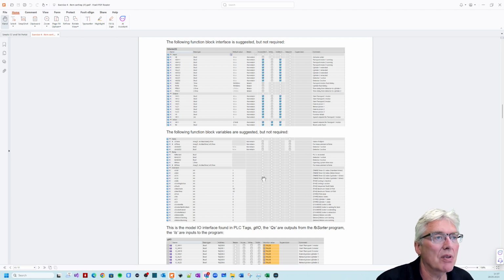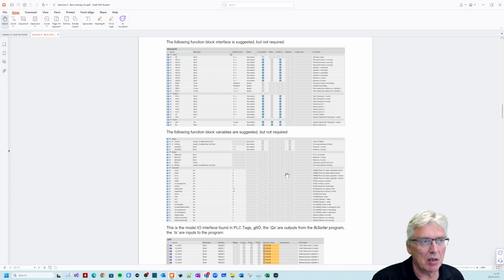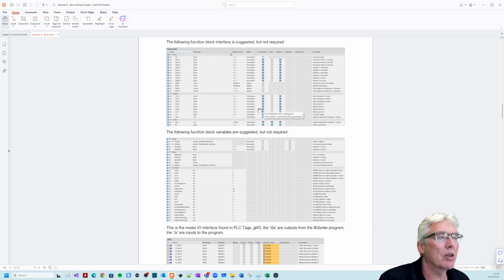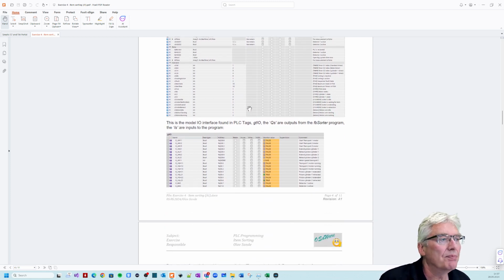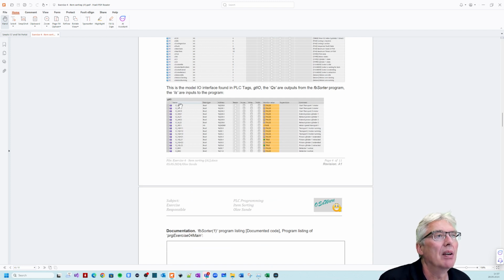If you stop it, is it stopping? If it doesn't, it's an error. And if the cylinder doesn't eject or retract, extend or retract, that's an error, and so on. And then you need a fault reaction. What should be the fault reaction in a system like this? Maybe you should just stop the system and wait until the error is corrected with a fault. I don't know. It's a little up to you.